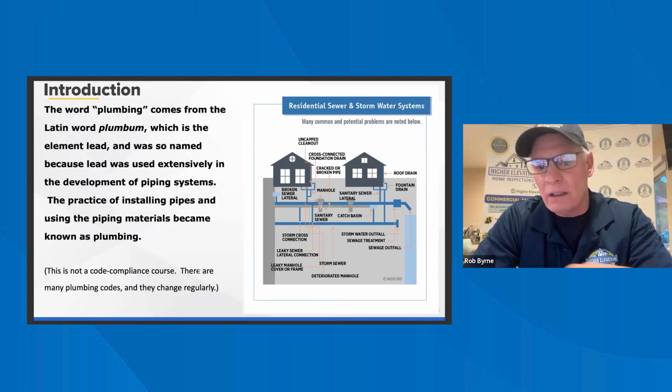Again, this is the cutaway version of a tankless water heater. What's good about it is to get yourself familiar with the air inlet, the exhaust. You're not going to open this up and start having conversations with your client, but you're going to look for various things: corrosion, rust. You just open it up visually and you can see, but it's good to know these things.